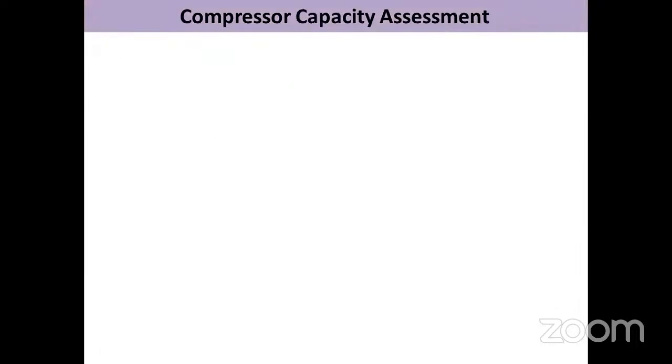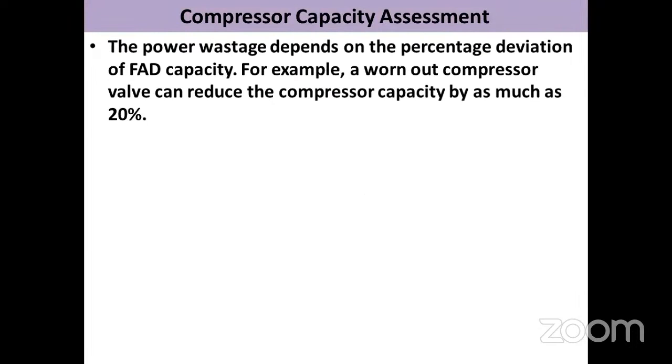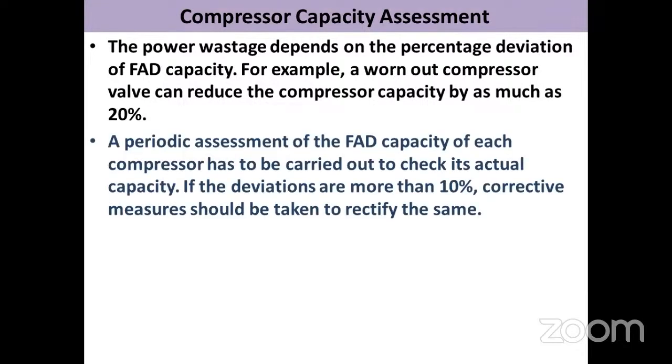Consuming more power. Compressor capacity assessment. FAD is a term we will be using, that is free air delivery. Periodic assessment of FAD is required. If the deviations are more than 10%, corrective action measures should be taken.